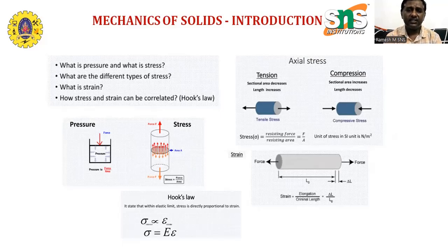Next is another basic concept: Hooke's law in strength of materials, that is, mechanics of solids. Hooke's law states that stress is directly proportional to strain within the elastic limit. That is a very important statement: within the elastic limit. Beyond the elastic limit, Hooke's law will not be valid.